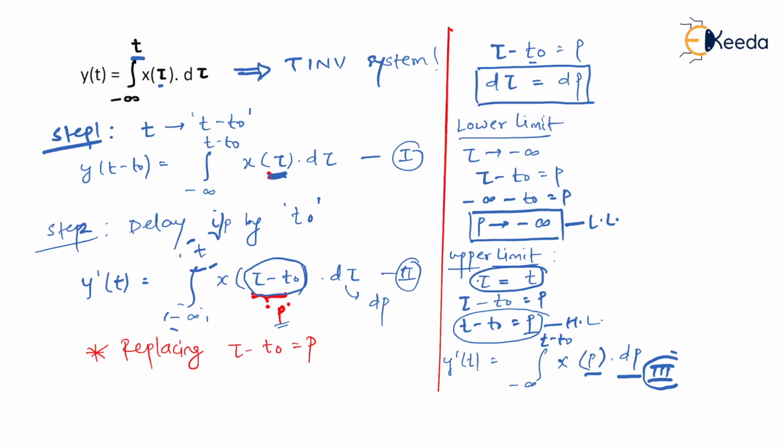But if you really don't want to go through a huge procedure, then you have to remember certain tricks, and those tricks are that you have to always check variable t with respect to input, right? So here neither scaling is done nor shifting is done, and let me tell you, shifting really doesn't matter, because if only shifting is done it remains a time invariant system only. This is what we have already seen with an example, right? So let's see the next example.